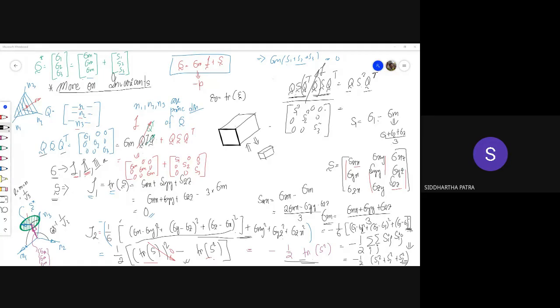Okay, I believe now you can try to derive it. Try to get that expression right there, involving sigma x and sigma y. And so you might notice here each tensor is represented in 3 forms. One is the global Cartesian form, where I'm writing it as sigma xx, sigma yy, sigma zz, sigma xy, yz, zx, etc.